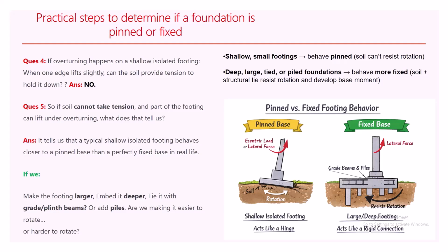And when you make your footing larger or your foundation goes deeper, you see that your foundation behaves more like a fixed support. That is why the plinth beam is very important in construction. Even when you design as a structural engineer, you should provide your plinth beam in the sense that you have a soil test report or you understand that site, you know the nature of that site.